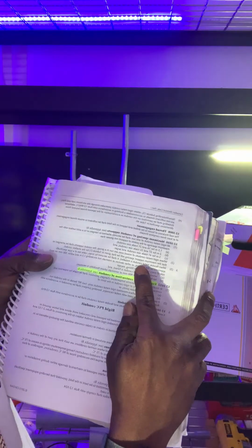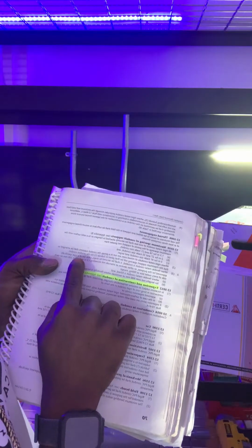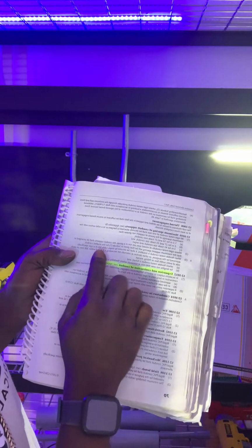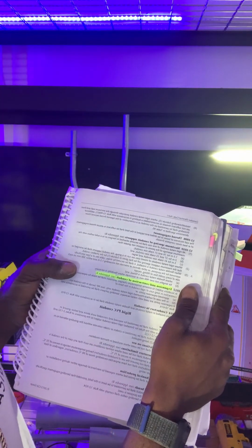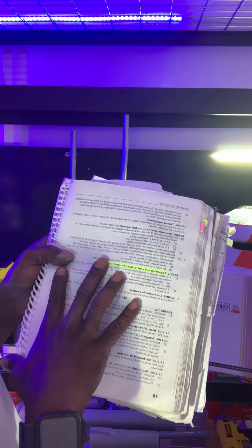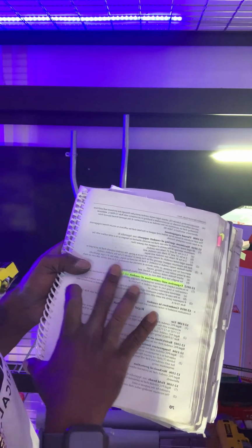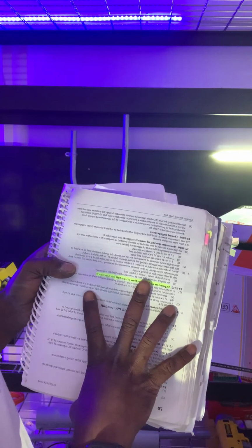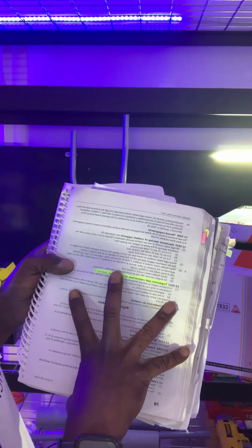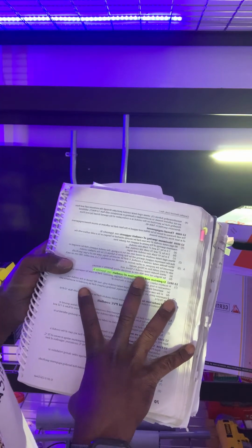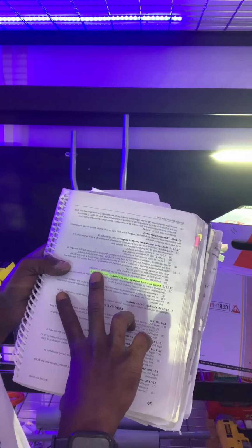3. When flexible metal conduit is installed, it shall be secured by straps, cables, ties, or a type specifically approved for the purpose or other devices at intervals not exceeding 1.5 meters and within 300 millimeters on each side of every outlet box or fitting, except where flexible metal conduit is fished, and B, for a length not over 900 millimeters at terminals where flexibility is necessary.